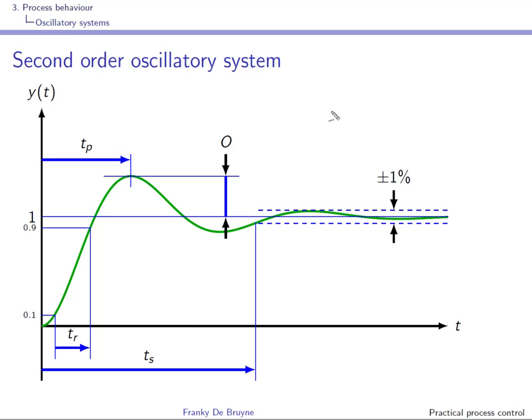So the input here is a unit step on the set point, and the response given here in green is this unit step closed loop response. And usually, if you have done a good design, PV will settle in such a way that PV corresponds to the set point, and since the set point here is a unit step, PV will settle to 1 over here, to a variation of 1.